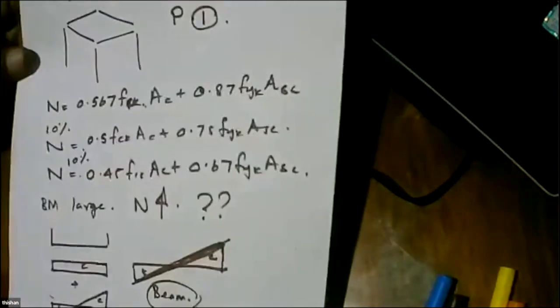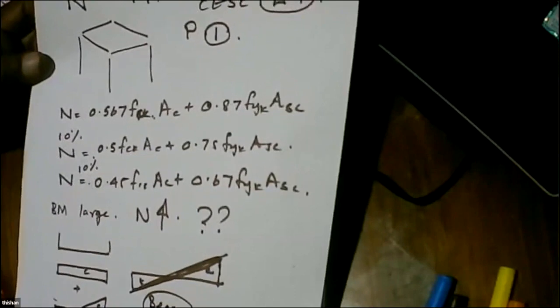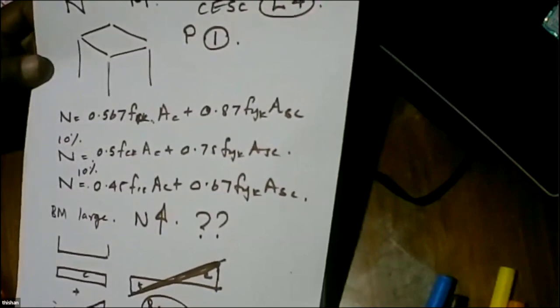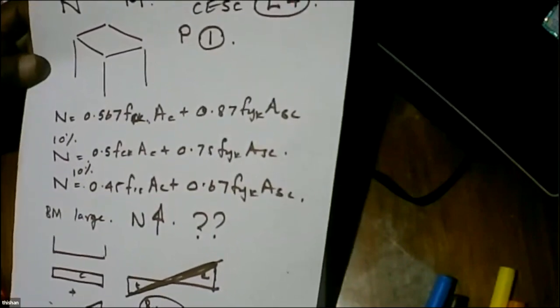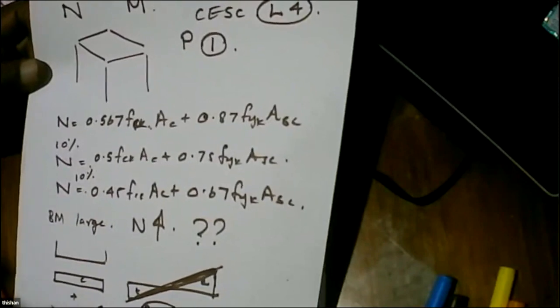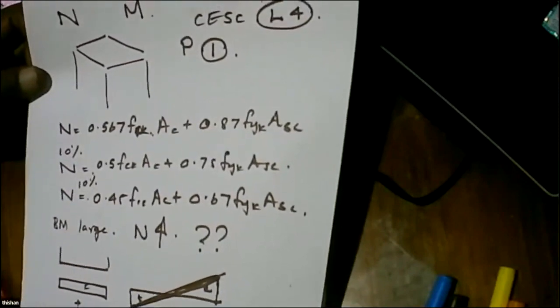Stress is equal to force divided by area. So force is equal to stress multiplied by area. So we get two materials under stress. One is concrete, one is steel, and the total load is carried by steel and concrete. So we'll finally end up with very simple equations like this. Simple equations that you can just write the moment you know the theory. So that's the beauty of starting teaching with columns. And then I explained many things like earthquake resistance, how to do earthquake detailing. So a lot of things were discussed last time.